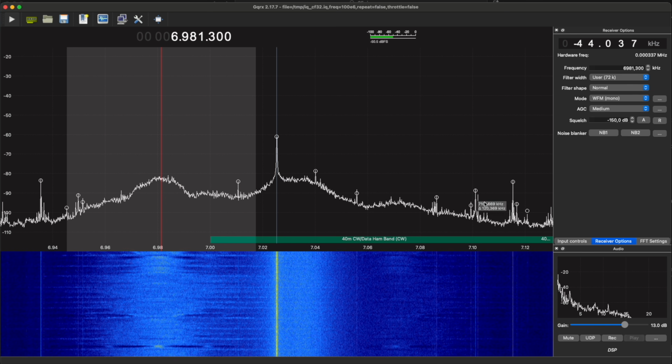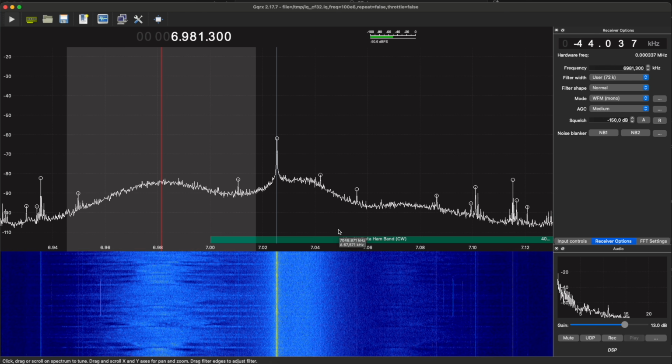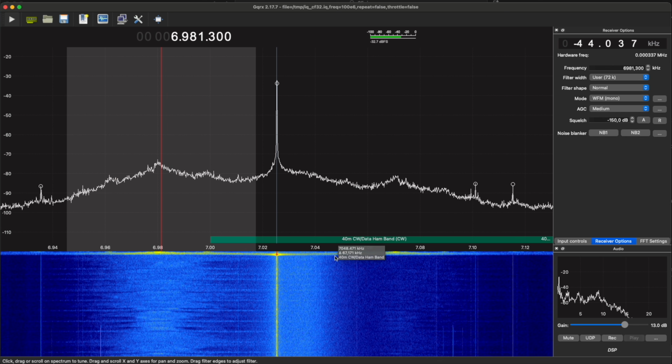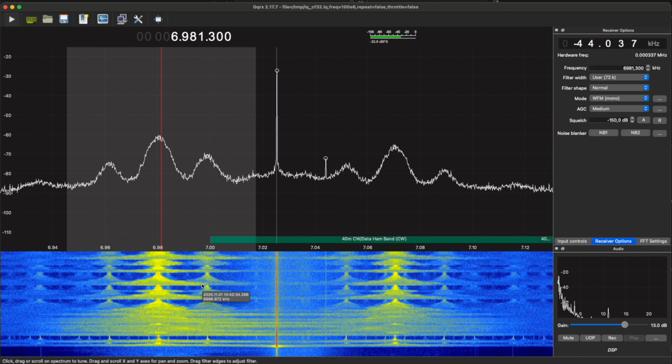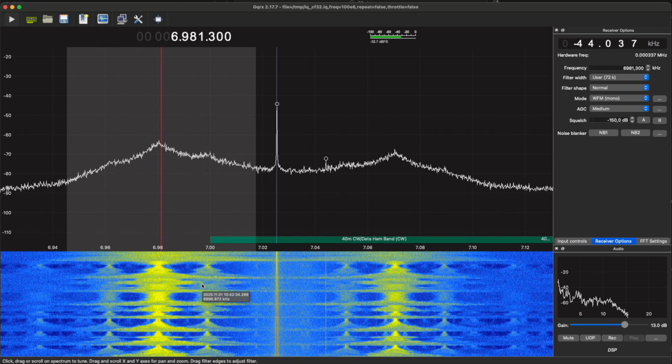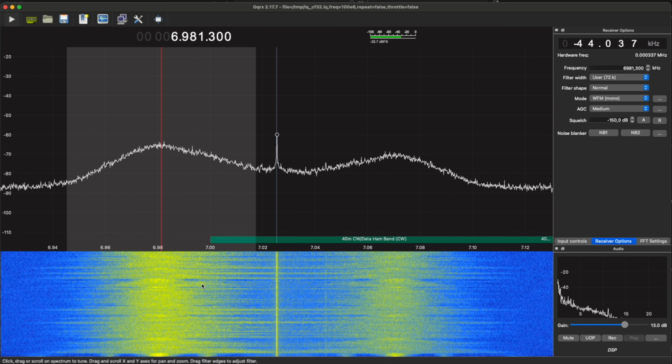That's pretty decent reception, but I better change the station before I get a copyright strike for playing Sabrina Carpenter. I've set all the channels to tune 50 kHz above center, so we're not affected so much by the DC center spike. But maybe I should have set them a bit further away.